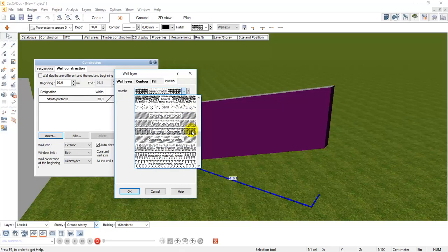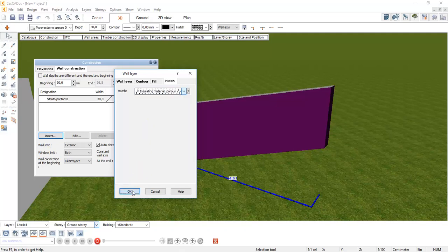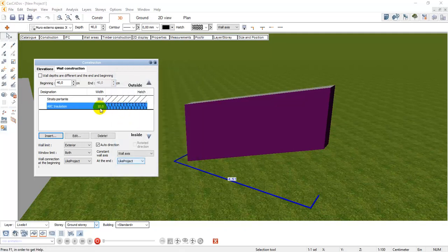This is, you see, this is the insulation hatching, and so on. And I will move this new layer with this arrow outside or inside, and so you can control the position of your new layer. You can create as many layers as you want, 5, 6, what you want. So in this way you can manage the 2D views, but of course you also have a 3D result.